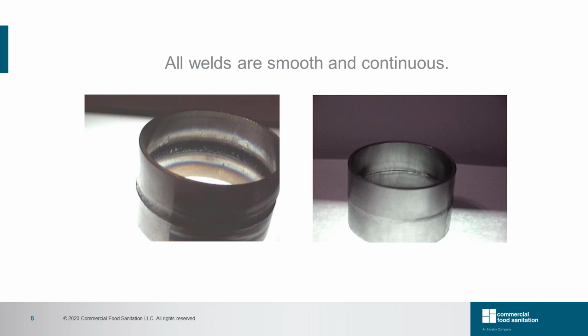Both images are examples of problematic welds for CIP, which is clean in place, cleaning, which can be found in pipelines. In the left image, stainless piping is welded with an inert gas purge, such as argon, for sanitary welds, which are common in pharmaceutical and food, particularly dairy, industries. Stainless steel oxidizes quickly at elevated temperatures without the gas purge. This causes a non-sanitary oxidized weld.